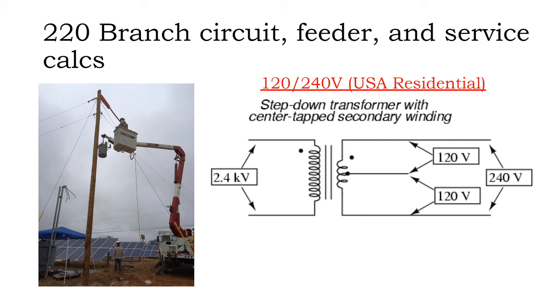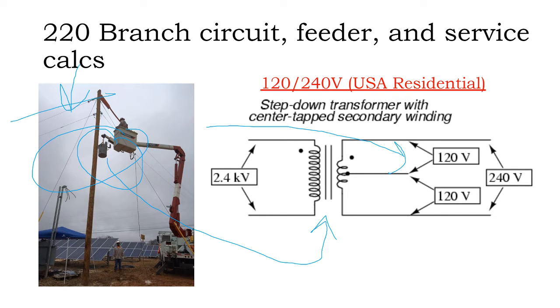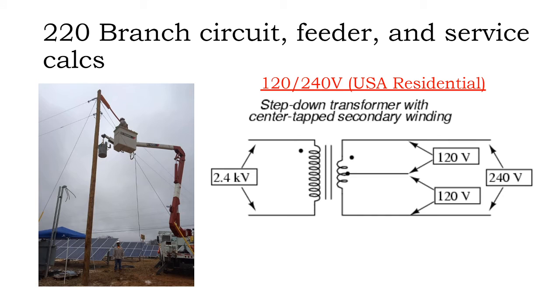Now these power ratings, 440, 208 three-phase, 120/240 split phase, literally have to do with the physical wiring of power that goes into the utility transformer that converts higher voltage distribution power into lower voltage building power. Whatever that distribution circuit is feeding, they get a transformer hanging on, and that electricity spins through these cables, and the voltage and amperage is manipulated that way. It's easier to do with alternating current rather than direct current. That's why our grid is built out with alternating current.